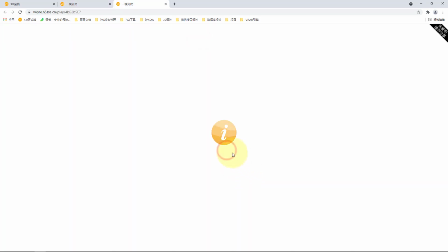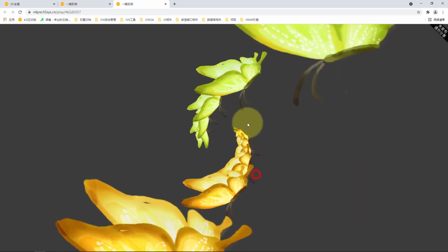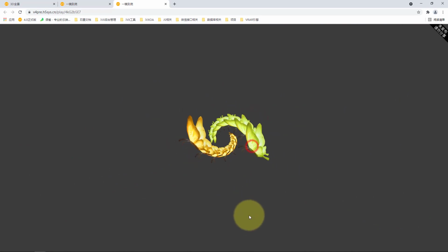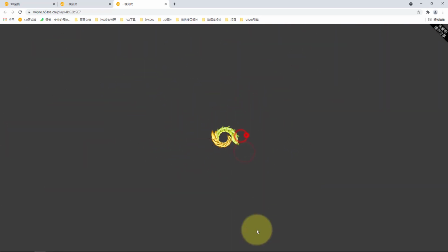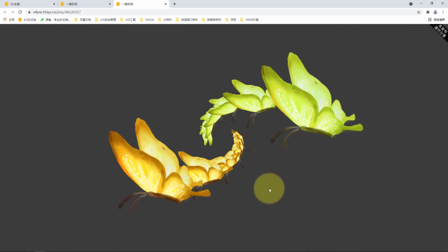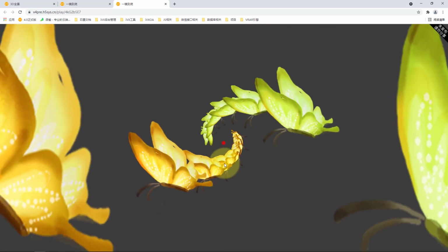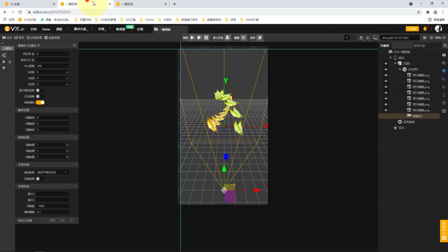has appeared, but you can see that if I slide very far, it will become very small. If I cross, there will be no content in the whole screen, so here we can control one of its gestures. One direction of the z-axis is also set. We can see that it has a maximum z and a minimum z here. We can notice that its camera is located at a position with a center distance of 300 at present. Therefore, it has a positive distance of 300. The default coordinate here is 0.